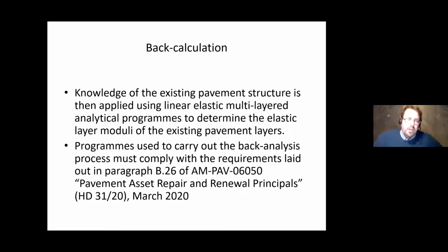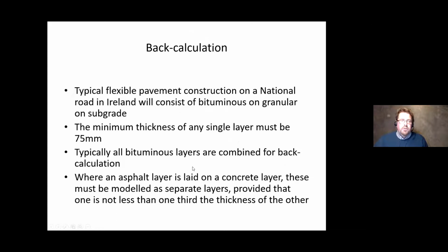So what then actually happens in the FWD is they carry out a process of back calculation to get to the structure and determine your overlay requirements. When you've carried out your structural testing and your core depths, this back calculation process is carried out using a multi-layer linear elastic system which determines the actual moduli of the pavement. The programs to be used to carry this out are listed here in HT31. I'll fly through this because it's something the operators will know, but the slides will be available if you need to look back over it.